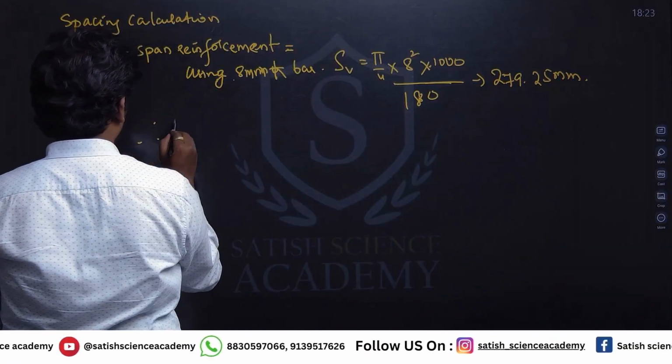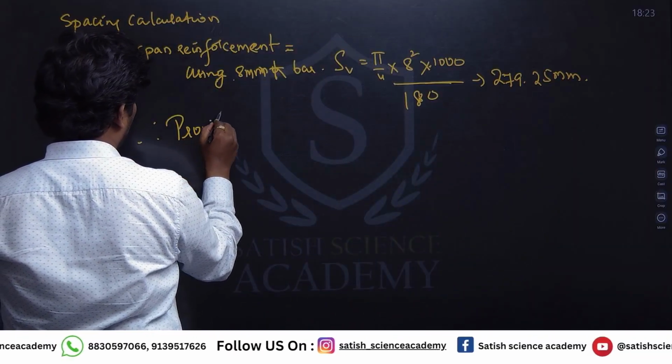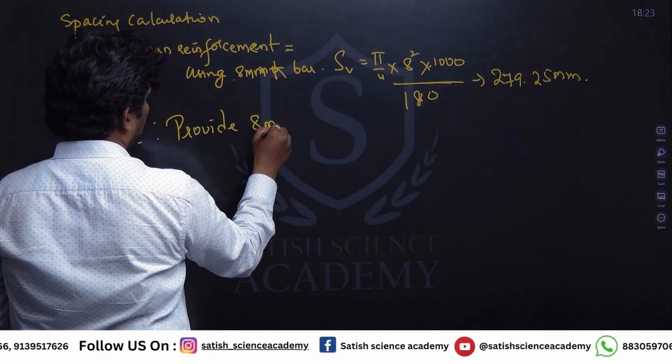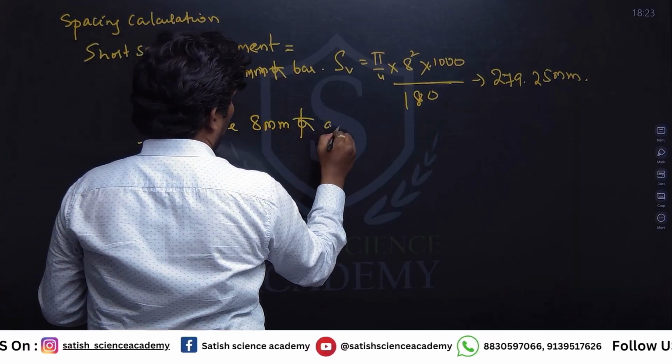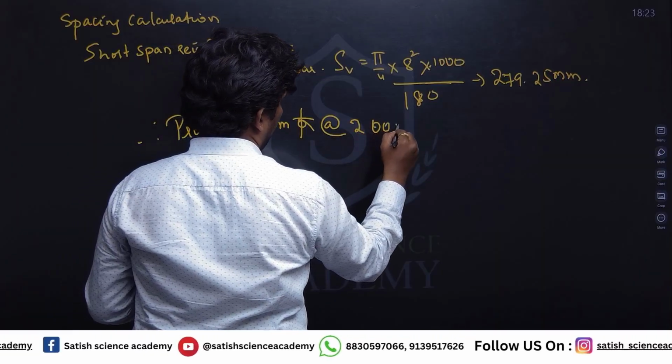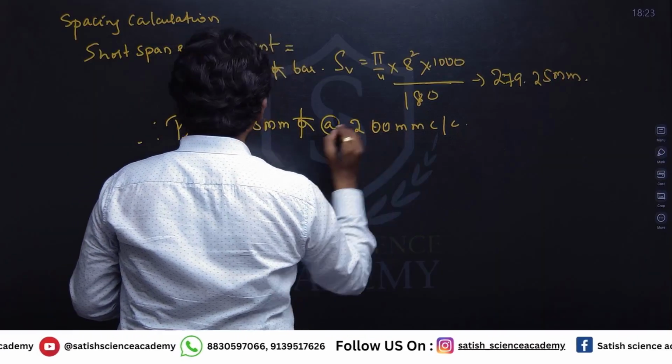Therefore provide 8 mm dia at 200 mm center to center.